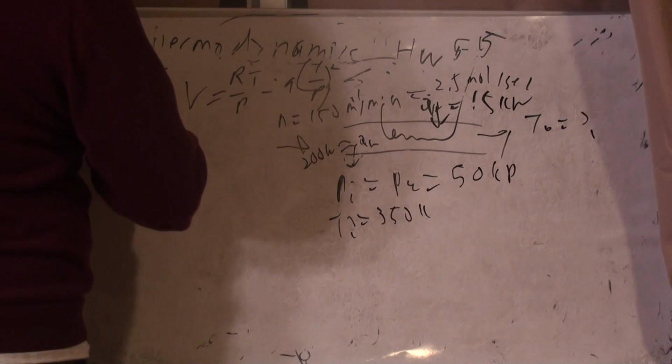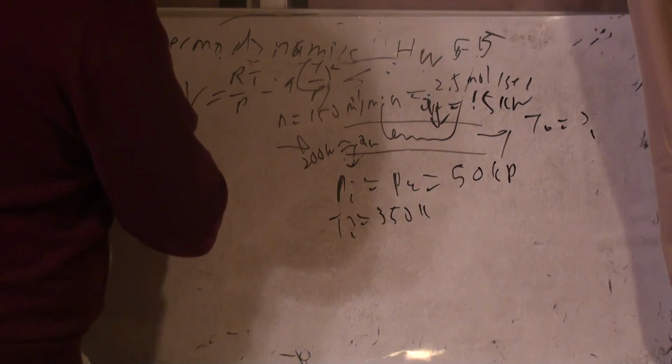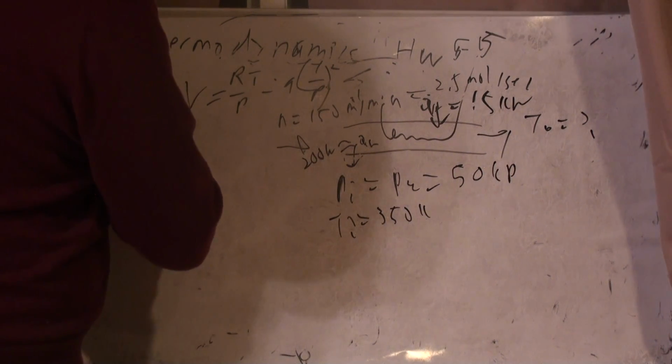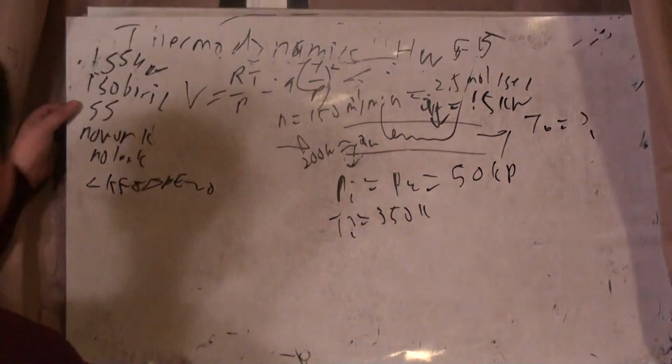Okay, well, so I'm going to assume it's isobaric. I'm going to assume it's steady state. I'm going to assume there's no work. I don't really see any rotating shafts. There's electrical work, but I like to consider that more of a heat term. But I don't have any rotating shafts. I don't have any boundary expansions. I don't have anything like that. I'm going to assume that there's no leaks. I'm also going to assume that delta KE and delta PE are approximately 0. And that's about all I can assume. Everything else is going to have to be in depth.